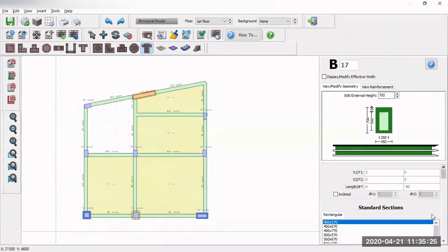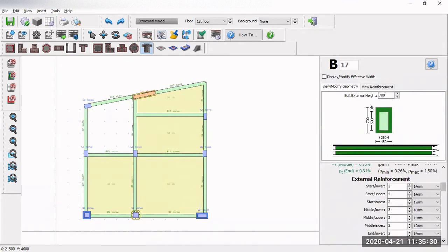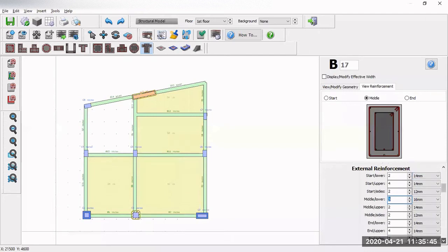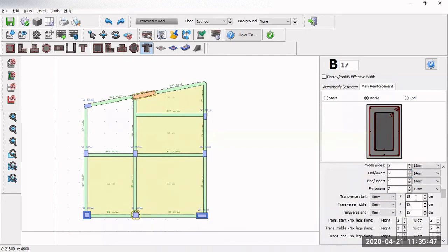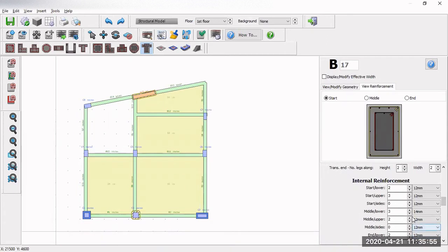And let me go to the top here. These are the dimensions. And the reinforcement rebar, maybe let us try to apply the same thing. Okay, I will use all the default values, keep it simple. All right, but you can feel free, after you do the design, you can define your rebar size from here. And the spacing, I provide a much more closer one, this one here. Then the internal you might need to change to our original one.